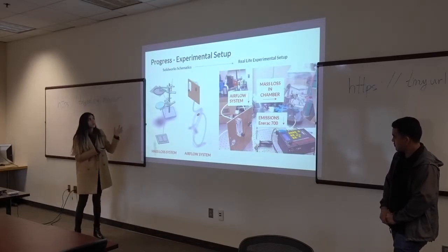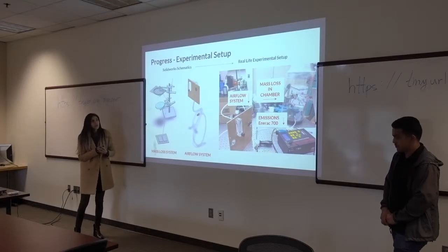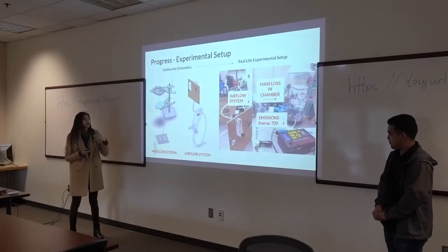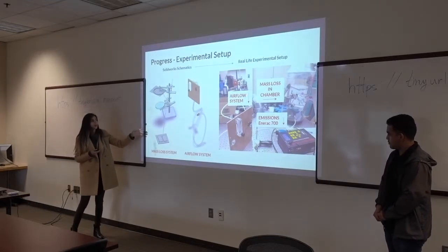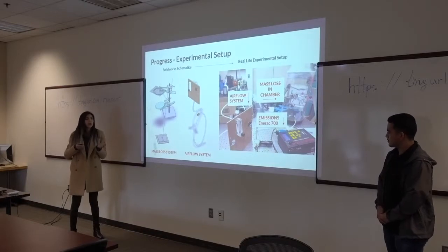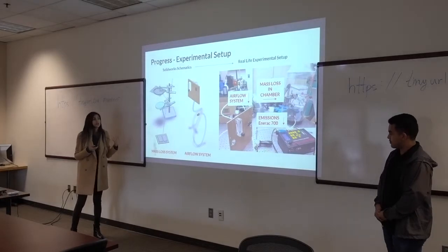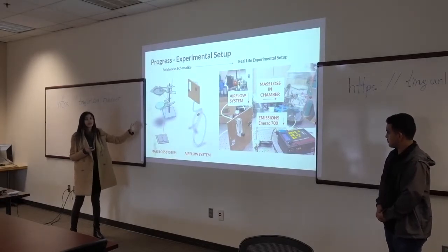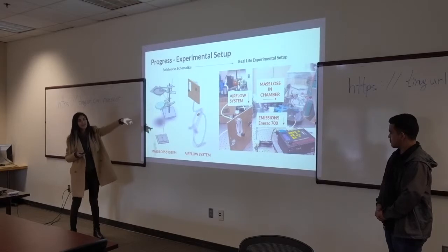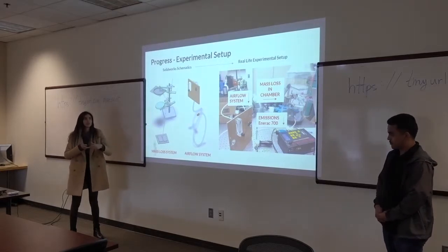We need these SolidWorks schematics for the combustion chamber because when there are design issues, we can go back into the schematics and iterate on them, to visualize what changes would look like and perform simulation testing to ensure they would work. We have a way of validating analytically or theoretically first, and then actually making these design changes.